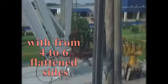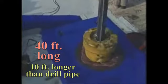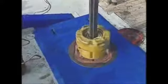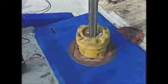The Kelly pipe is the topmost joint of the drill string with from 4 to 6 flattened sides and is 40 feet long, 10 feet longer than drill pipe. The Kelly or top drive transfers the torque, or rotating power, down the drill string to the bit, allowing the rock to be cut. Let's now examine the drill bit and its colorful history.